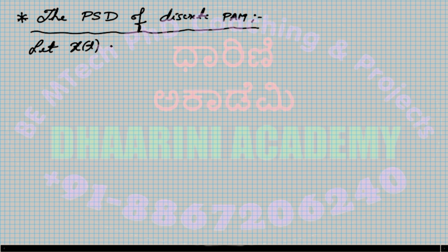Generally you can represent it using the following equation. This is a summation, a little bit of mathematics today. It is the sum over k from minus infinity to plus infinity of a_k, the amplitude, times a pulse denoted by v of t minus k times T_b.